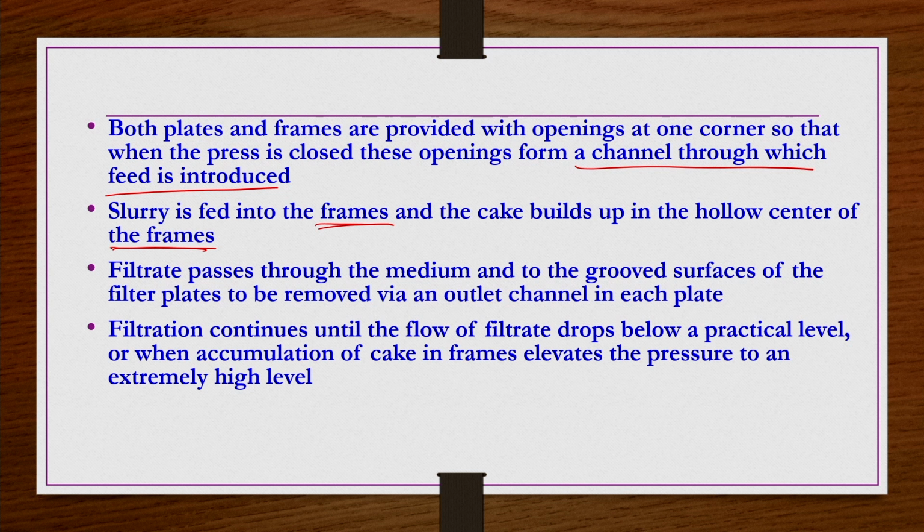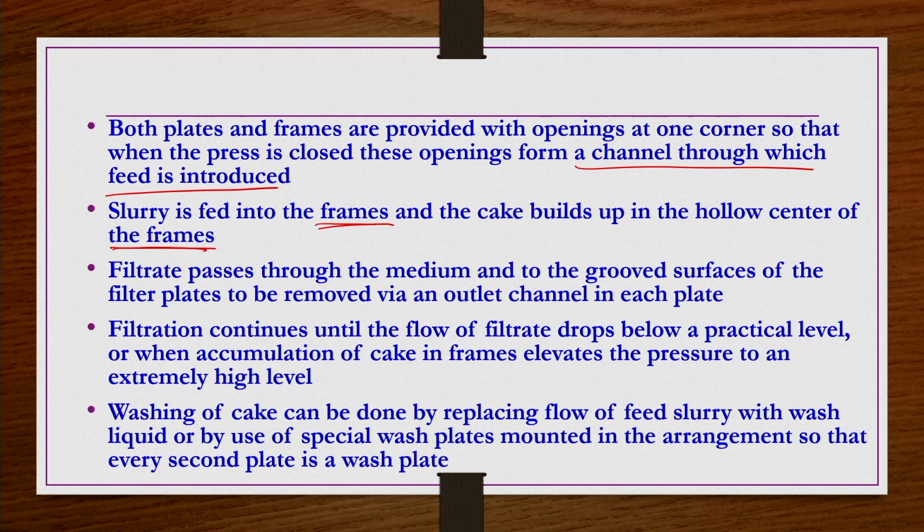Okay. Under such conditions, you can understand that the hollow frame area must be completely occupied by the solids, and then further filtrate might not be coming properly. So then you have to stop the process and clear the frames by a washing process, and then you redo the separation once you clear the cakes that have been deposited. Okay. Washing of cake can be done by replacing the flow of feed slurry with wash liquid,